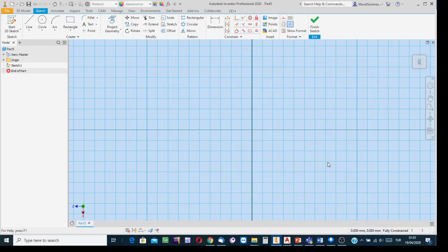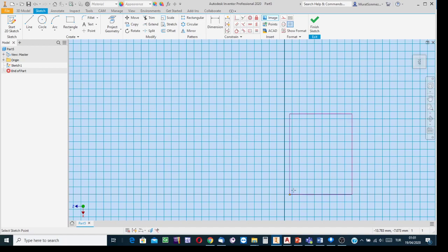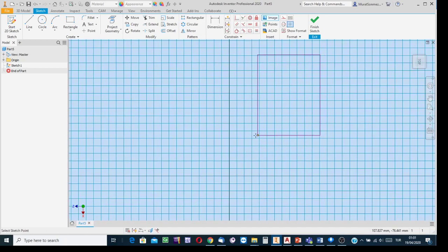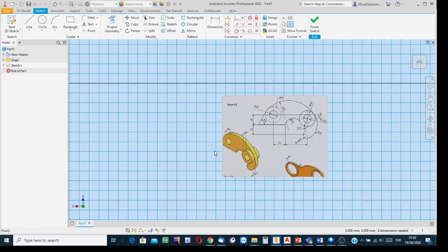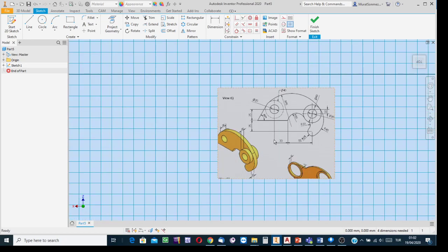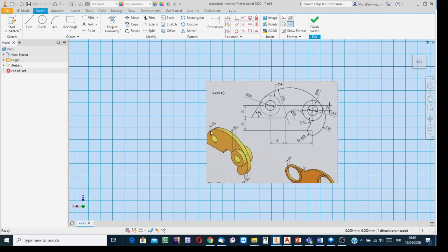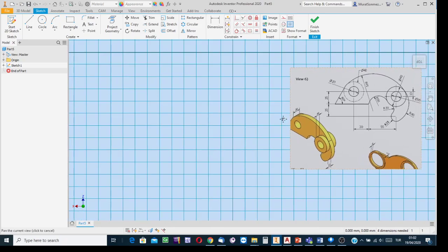And then say Open. And then yes, zoom out. This rectangle corresponds to the frame of that picture. Anchor it arbitrarily with a click. And then press the Escape button. If you couldn't find the pasted picture in a suitable orientation, then using the viewing cube, clicking on the bended arrows, you can rotate the sketch plane together with its content and have the screenshot as it is shown on the worksheet.